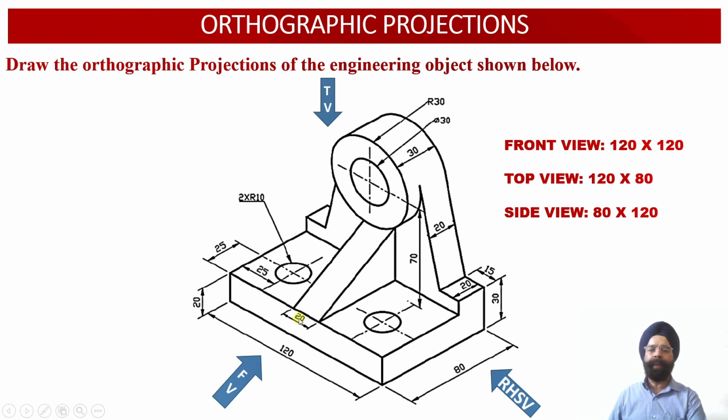So here we have to combine different elements of the solid in order to evaluate the total height of the solid. Now we can check corresponding to this horizontal web, which happens to be element number 1. The height of this horizontal web happens to be equal to 20 millimeter. Similarly, corresponding to this vertical web, which is lying on the rear side of the solid, the center point of the hole, which is going to lie on the top surface of this vertical web, is 70 millimeter.